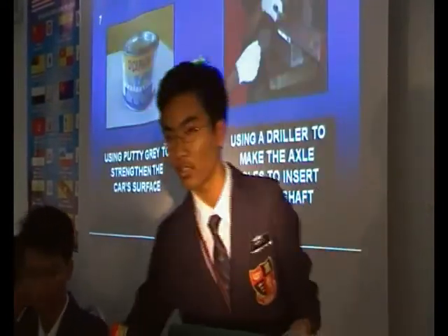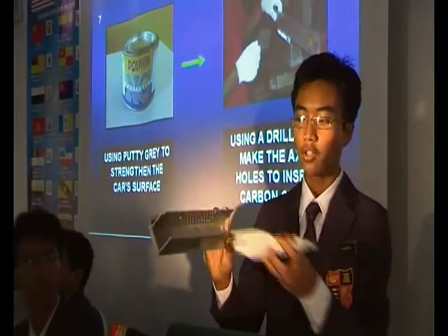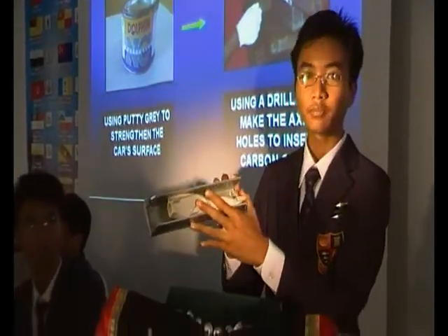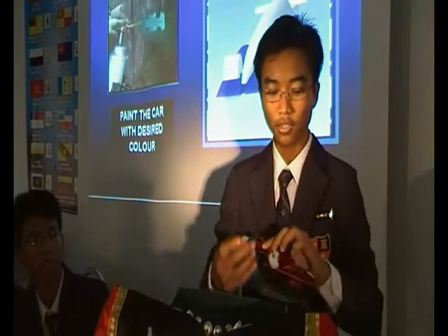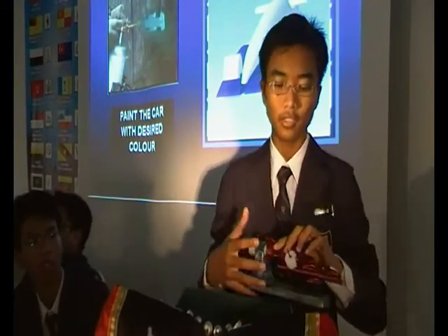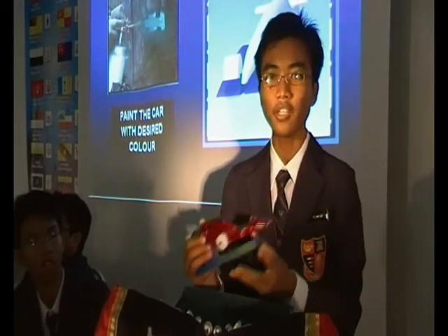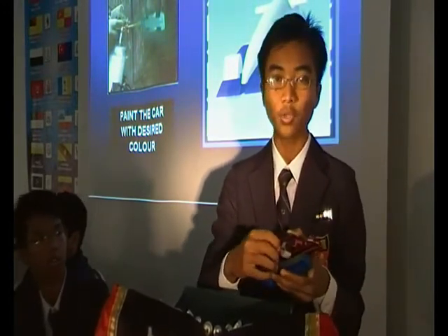The axle hole is drilled using a template that is made for the car so that the axle hole is straight. A silver undercoat is painted before the car is sprayed with the finishing color. To make the car look better, a clear lacquer is applied. A carbon elastic shaft is inserted into the drilled hole, and the tires are permanently assembled between two stoppers to prevent the tires from colliding with the body and slipping away.